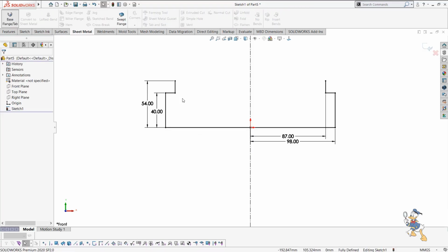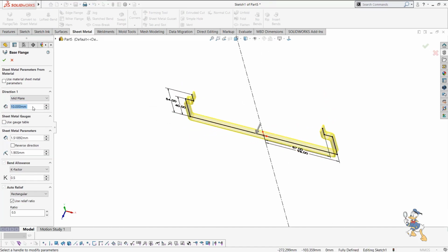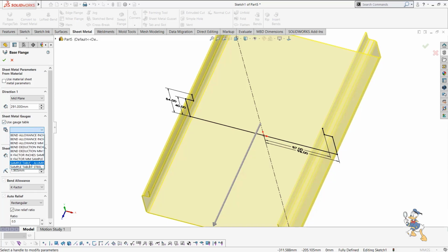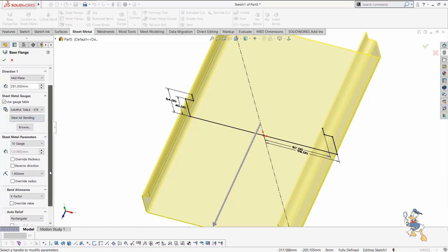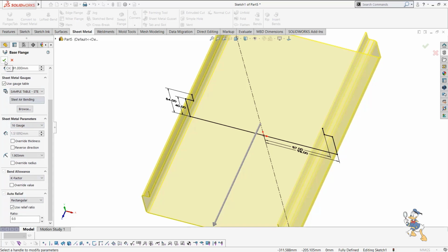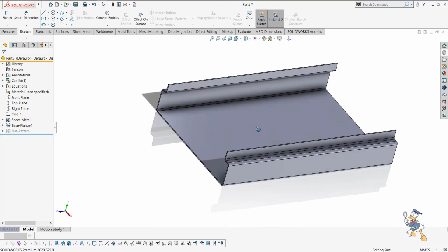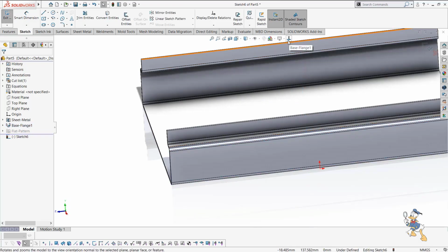Now we can move forward to make it a realistic view for the sheet metal component. Let us assume we define a dimension of 291 mm, and we can select a gauge table as well. Here we have a gauge table. To select it, I just need to select a 16 gauge sheet. Right now everything is predefined, so I just need to check it out. So now the sheet metal component base feature is ready. This is the basic feature we need to start the sheet metal component with, the blank command.